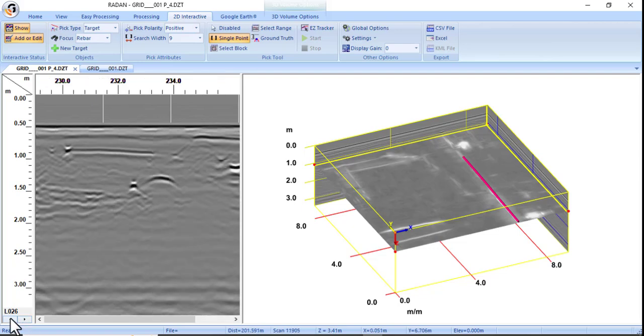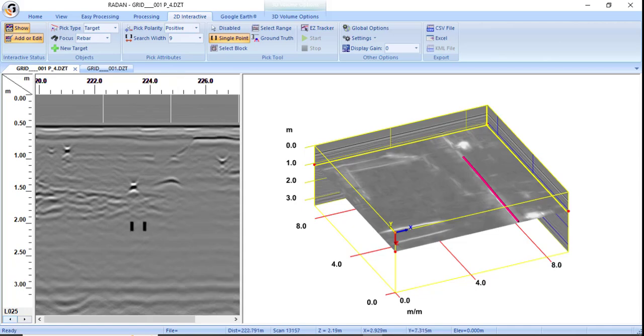And by the way, you can see that some hyperbolas do not coincide or collapse at the top, and this occurs because there are a bunch of hyperbolas, and if you need to migrate them accurately, you need to select several velocities and tell the program to make migration according to these velocities.